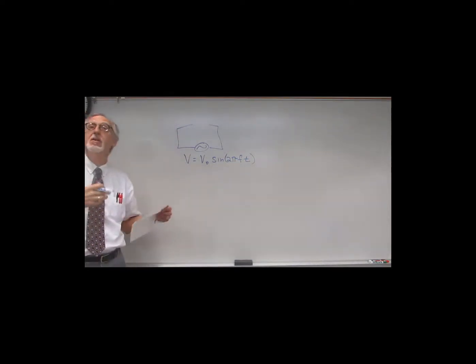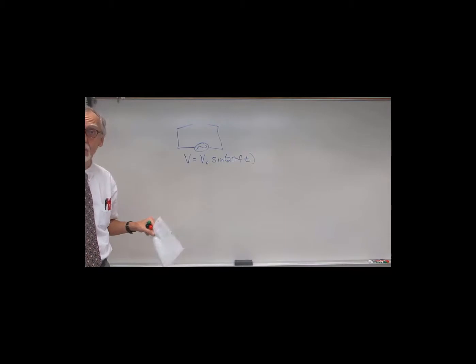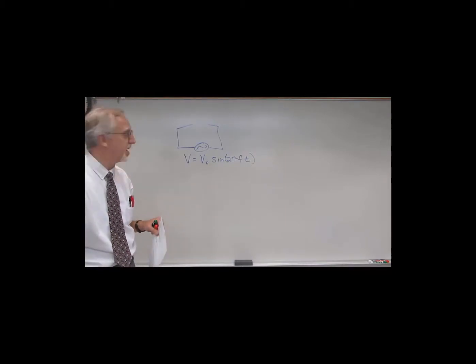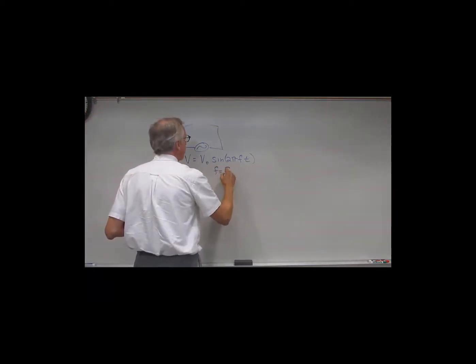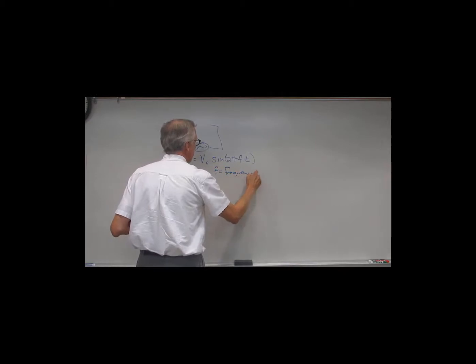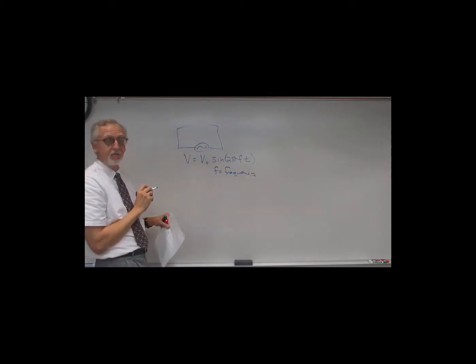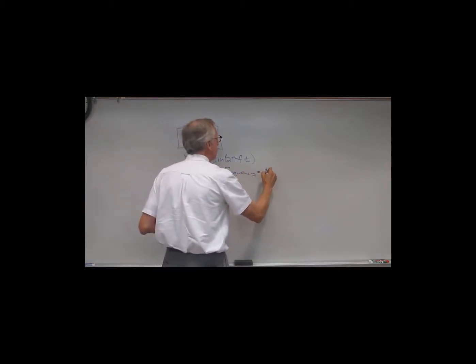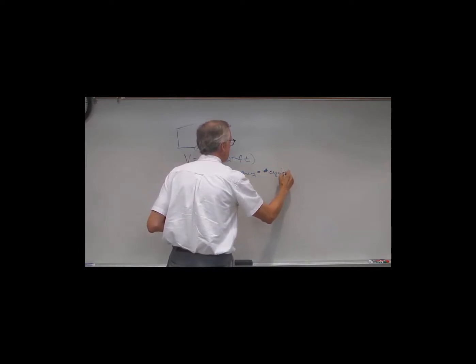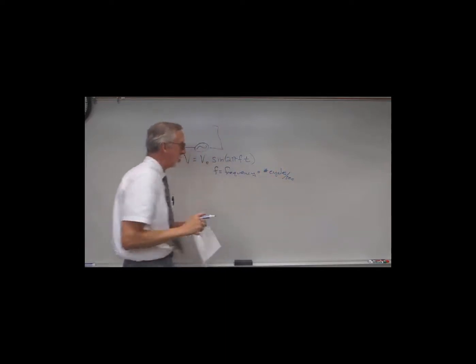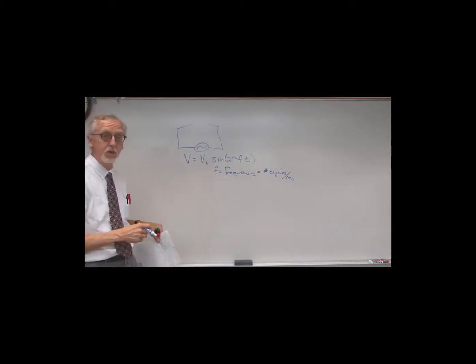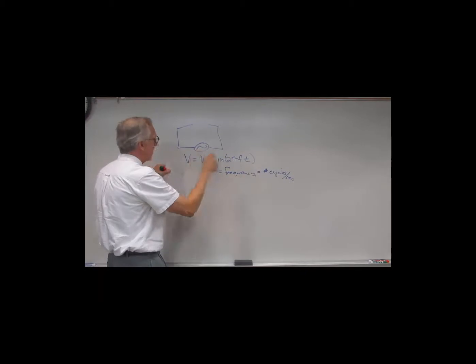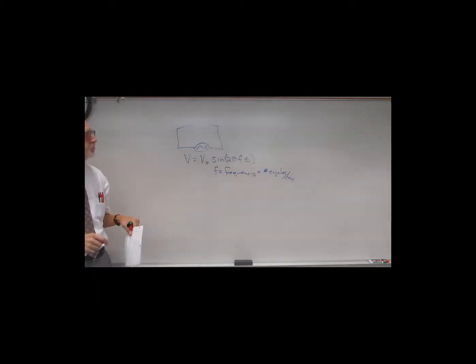So if you'll remember, this is something maybe familiar back when we were looking at simple harmonic motion back from 1111, where f is the ordinary frequency of the voltage, which tells us the number of cycles per second that our voltage is oscillating. So if the frequency was, say, 10 hertz, that means this is oscillating back and forth 10 times per second.